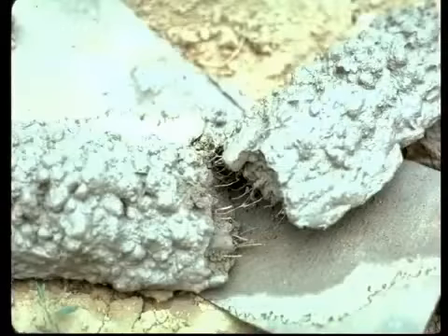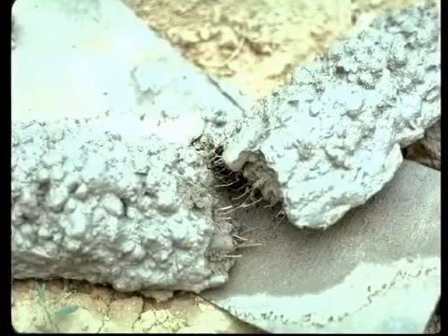Technically, the fibers are so rubber band-like compared to concrete that they do not reinforce concrete the way steel does. The fibers are marketed as a replacement for welded wire mesh, and I'm okay with that approach because the mesh provides so little. At least these fibers provide something in minimizing or delaying the plastic shrinkage cracking. That completes our section on reinforcement. We'll move to the last section on curing.